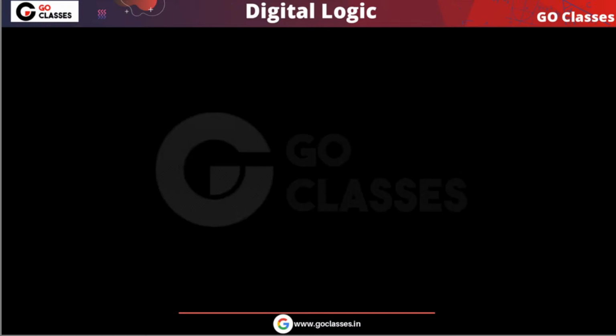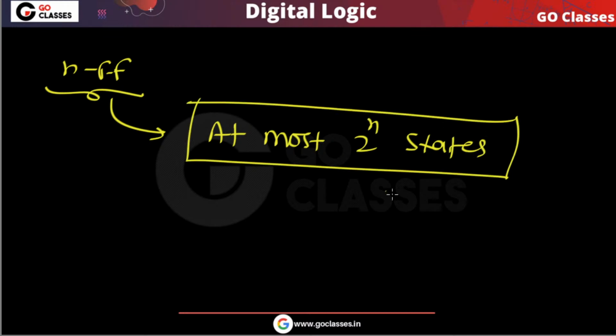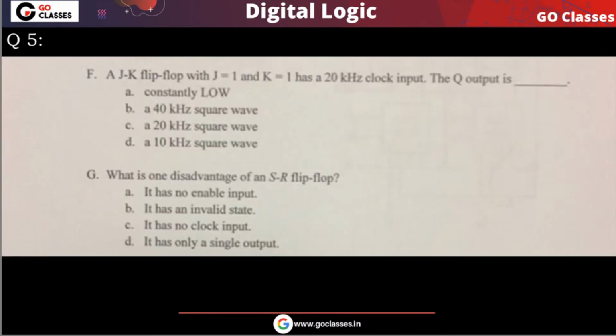Remember, if you have a total of n flip-flops, using n flip-flops, at most 2 power n states you can have in your circuit. So this is the idea. Here you can notice, if you want 15 states, then at least 4 flip-flops you need. So the answer will be 4. Tell me the answer for this question. What is the answer?